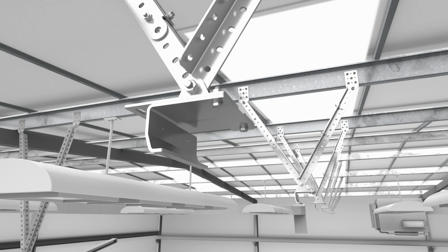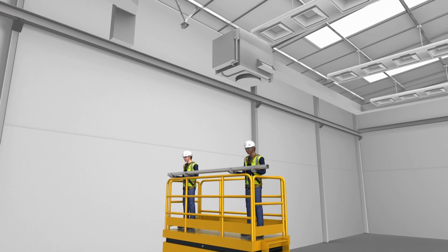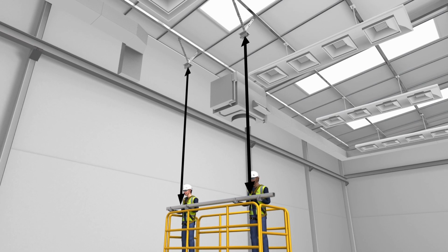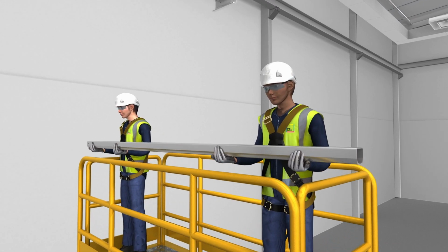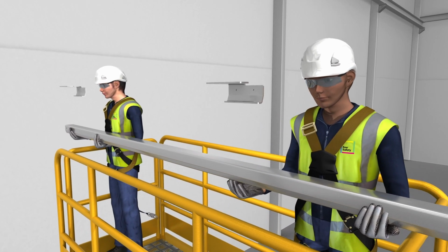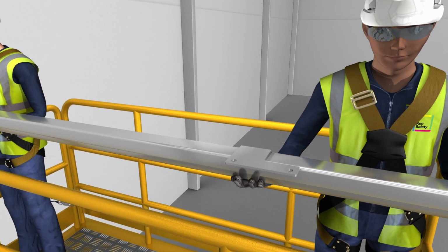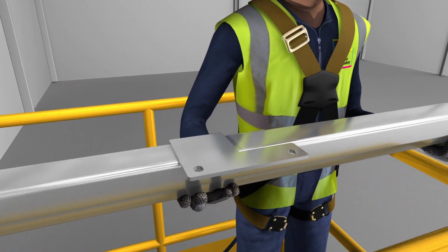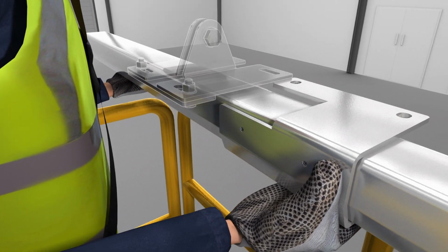Rail insertion is a two-person operation, and each operative should be positioned adjacent to or in close proximity of the fixed clamshell assemblies. Prior to raising the rigid rail into position, two additional half clamshells should be loosely positioned onto the top of the rigid rail. Assuming the opening of the previously fixed half clamshells is facing you in preparation for rail insertion, the additional half clamshells must be positioned slightly right of their proposed final position.